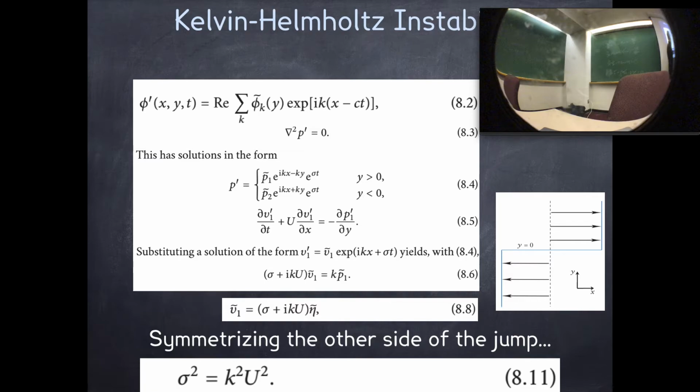What kind of equations are the equations of quantum mechanics, the Schrödinger equation? Linear. It's linear. So here, we can do a lot with the linear theory, but actually the real flow we're studying is nonlinear. So even though we can work hard on linear instability theory, and we definitely could have a semester-long class on it, it's actually not very interesting because it doesn't tell us much about real fluids, because they are nonlinear at leading order, and specifically turbulent fluids are nonlinear ones. So I'm trying to gloss over the linear instability aspects of this, but give you a hint as to how it works. So we're going to move quickly on to turbulence from here.